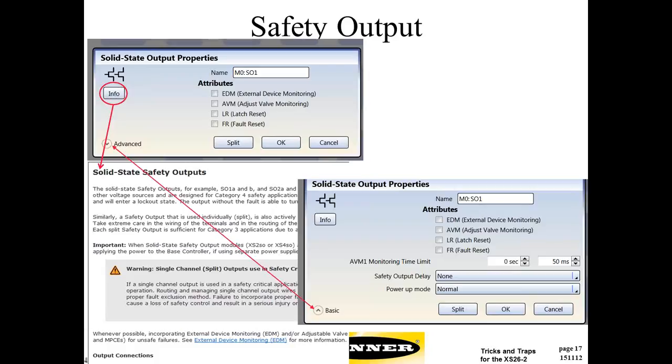another power supply. Also, anytime that you have any thoughts or questions, like, gee, what does this part do? You click on the info and that pulls up that section of the manual already indexed for you. Depending on the tile, if I have both advanced and basic functions, these happen to be the basic. This is a toggle, and here are some of the advanced functions. This is where you set up on, off delay, etc.